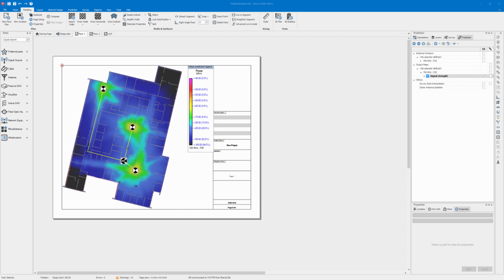And in effect, someone standing further from an antenna, or at a region of the floor plan where the uplink signal is weaker, will not benefit from the maximum gain of the network, specifically the BDA, and therefore cause a near-far effect. And of course, this output map assumes that the BDA is a wideband BDA and attenuation is added by the AGC, or that both UE are on the same channel.